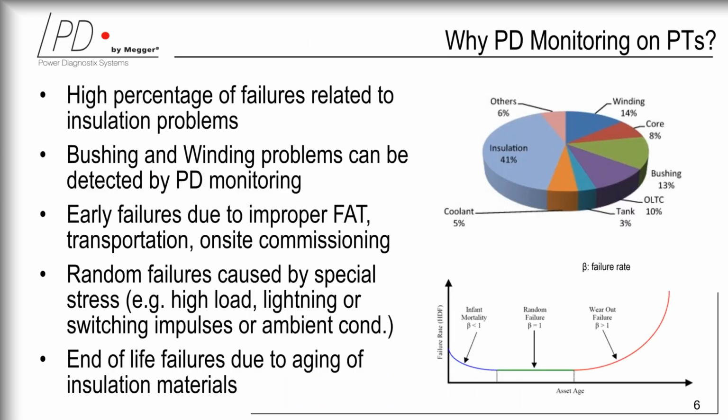If we look again at the life of a transformer, we can speak about the typical bathtub curve that starts with the beginning when the asset has a very young age, and of course then there is a period of life when, generally speaking, nothing happens, and then towards the end of life, 30, 40 years depends, we need to pay special attention because the wear out and the failures can be more prominent.